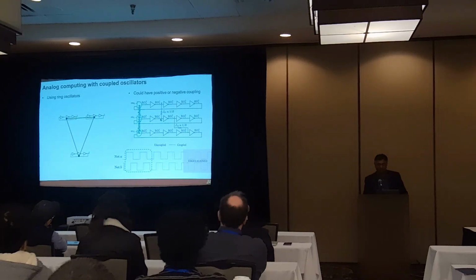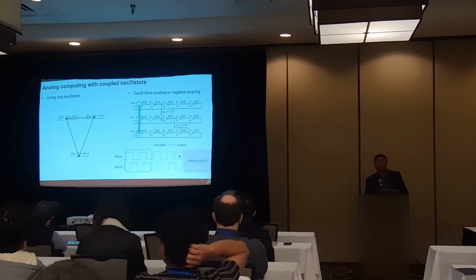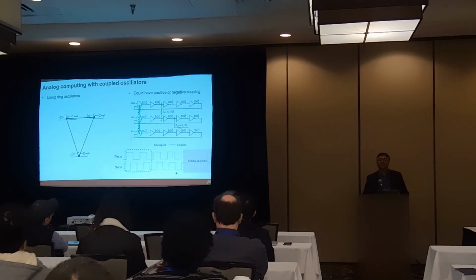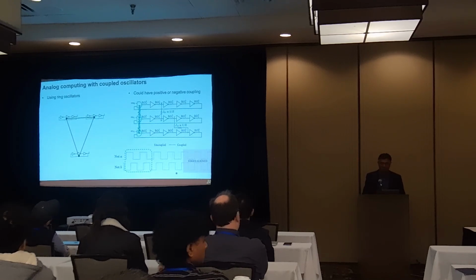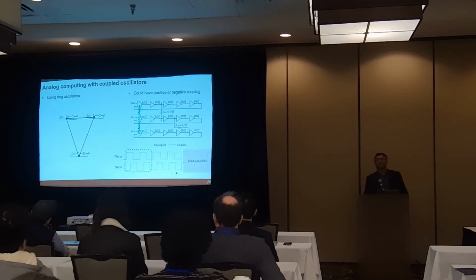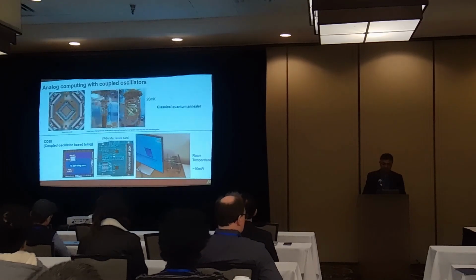If I look at the effect on B, when this is low, this is trying to rise. A is already high, so if B is trying to rise and A is high, this is actually helping the rise. So it's going to speed up the rise and make it come a little earlier. And eventually, as this goes down and this speeds up, they're actually going to lock into phase over here. Right? So that's the notion of how you can use ring oscillators to create coupling and get things to work. And that basically gets you to building coupled oscillators using electronic components, which can operate at nanoseconds or microseconds at worst if you use something really bad, as opposed to seconds for a mechanical oscillator.